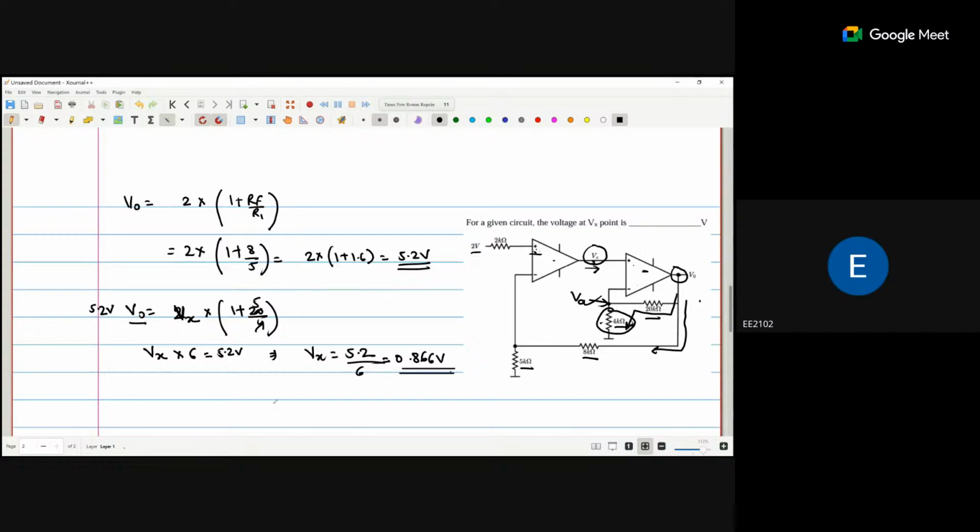So current is not passing from the operational amplifier. So because of this volt, we are not getting Vx, but we are getting V out. Now V out will drop across this resistor. So here there is some voltage, and that voltage will be Vx. Because of the second operational amplifier output, current is flowing from the output to the ground, and because of that we are getting this Vx. So don't be confused that the first operational amplifier is not working because it has negative feedback. So how do we get the Vx? Vx is not 0.